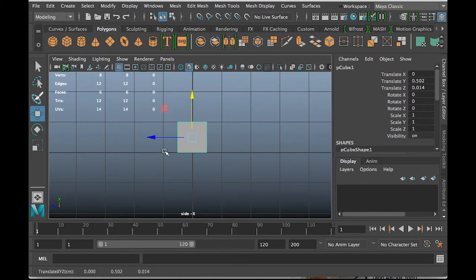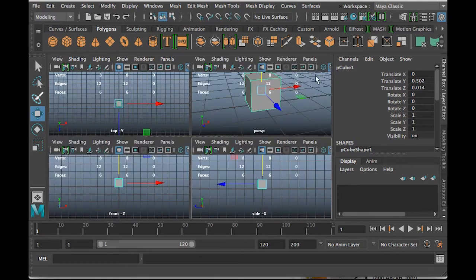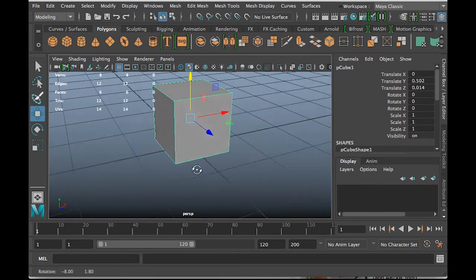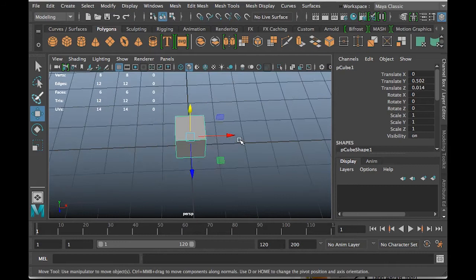Now try to position the cube somewhere on the floor. For the floor, I'm looking at this main grid line. I have two darker grid lines and I'm looking at its side view. When I go back to my perspective, it should be sitting quite okay. I can also do this in perspective. It's just a bit to move it.